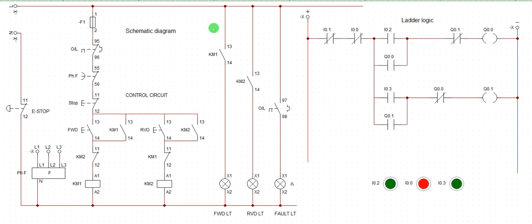All right, we use this particular control circuit to illustrate the sequence operation of a particular process. And this one, we use symbol of a component to represent the sequential manner in which a particular process is being controlled. This particular logic now is our ladder diagram. This is the particular diagram we use to write a program and download into a PLC.